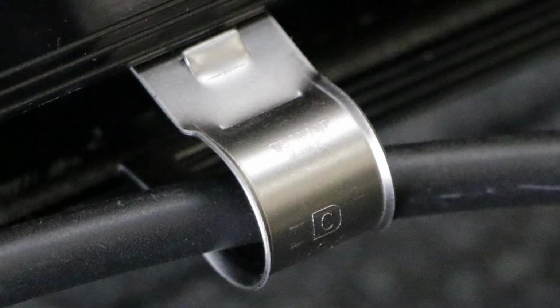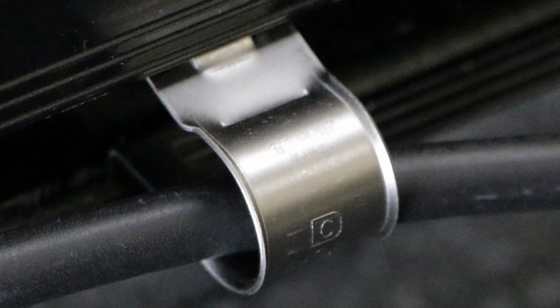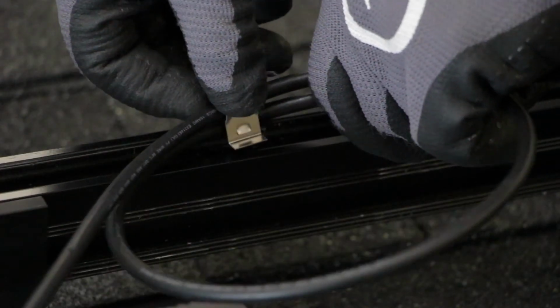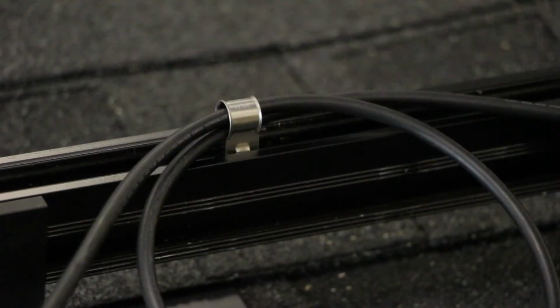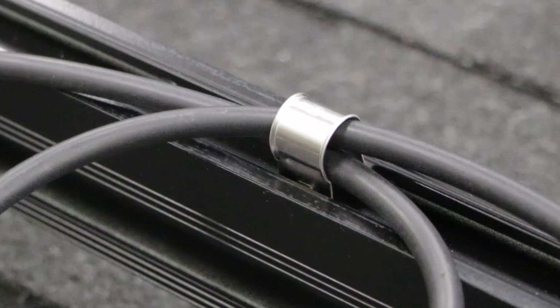When securing a single wire, the clip can be pushed in past the flanges on its sides, clicking in and staying secured at a smaller gauge. Follow basic wire management strategies to secure all of your PV wires and home run wiring to the QRail.